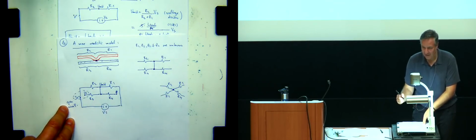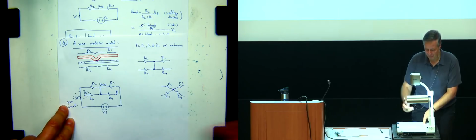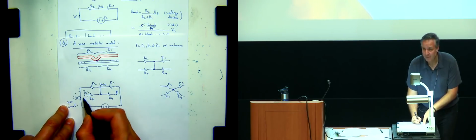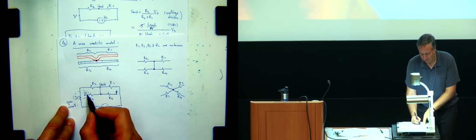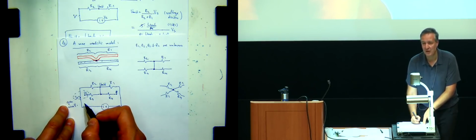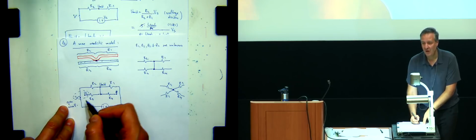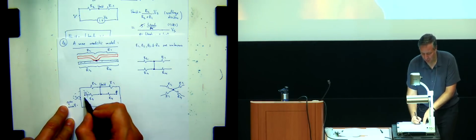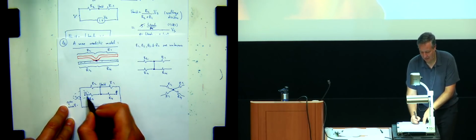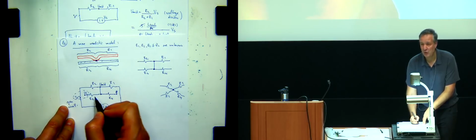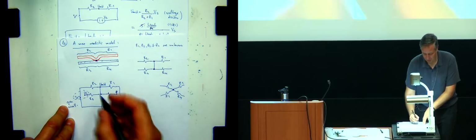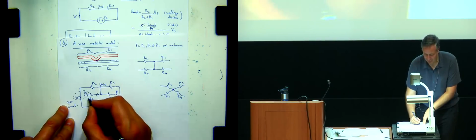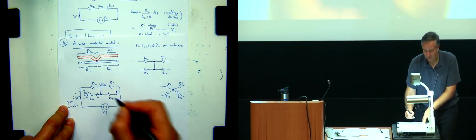Okay, so let me rephrase that just to insert one extra step. This is an open circuit, right? By the definition of the open circuit element, the current going into the open circuit is 0. By KCL, between this element and R3, that also means that the current through R3 is 0. Right? So it means that this current is 0, then this current is 0.